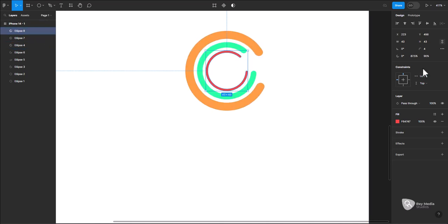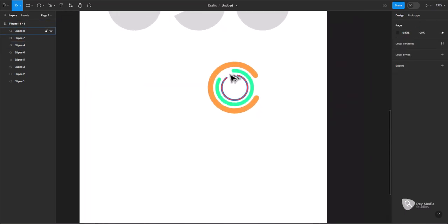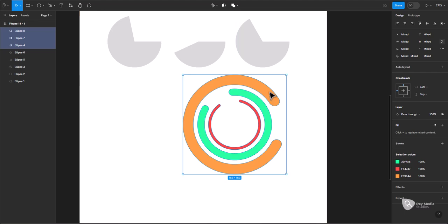Instead of turning it like this, we can decide to change the start to, say, -20, or -20 is small. Let's change it to -80, and this to 50. Or no, let's change this to 100. Good. So basically, that's a whole lot you can do with the ellipse tool.